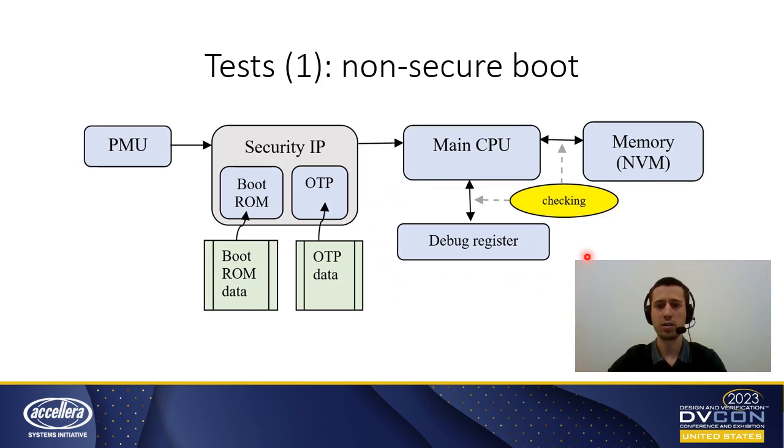So what do we check? We check that the main CPU executed these transfers correctly. In case it didn't, we need to find out why. This can be a bit tricky to identify because the flow could break at many steps. So it is a good idea to add checkers to other points in the system as well.